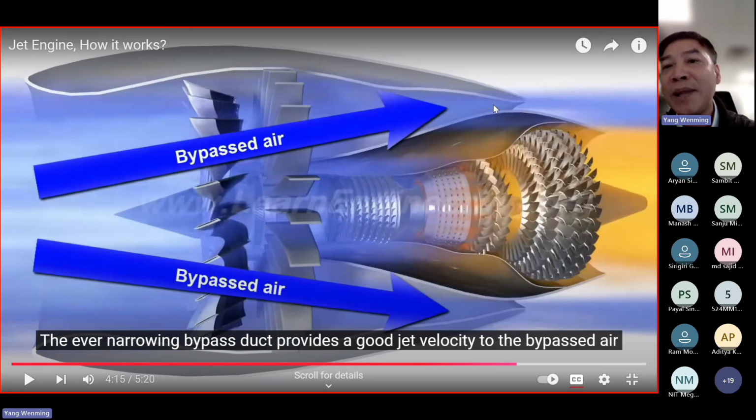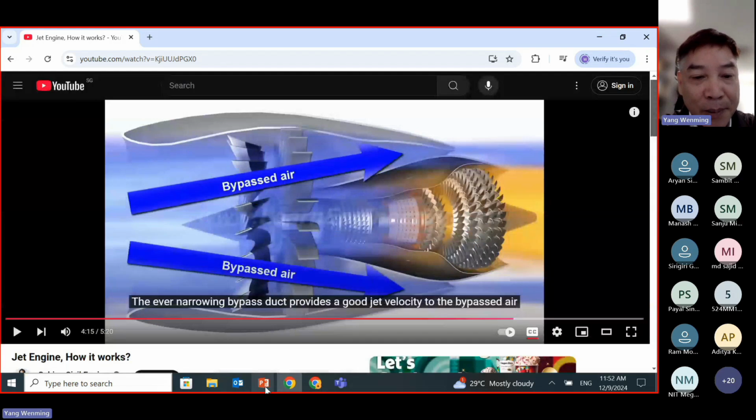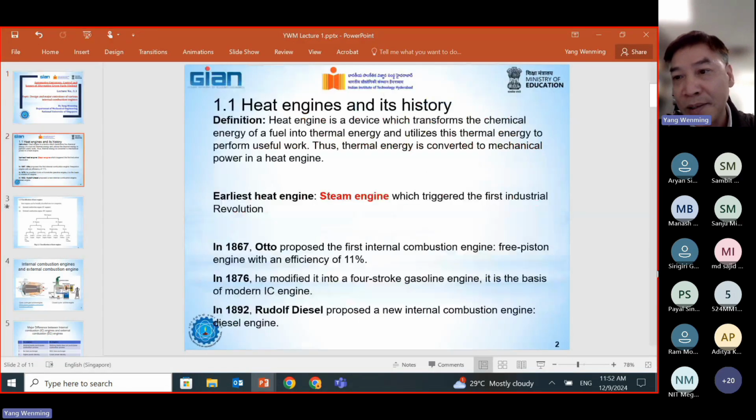So in this way, again, we increase velocity, and at the same time, because this fresh air will absorb heat energy from the jet engines, correct? It further increases the temperature. So in this way, we can significantly increase the pressure and the flow speed, thereby producing a greater thrust for the jet engines. Okay, so this is also a basic design and operating principle for jet engines. Okay, let's go back to the slides.